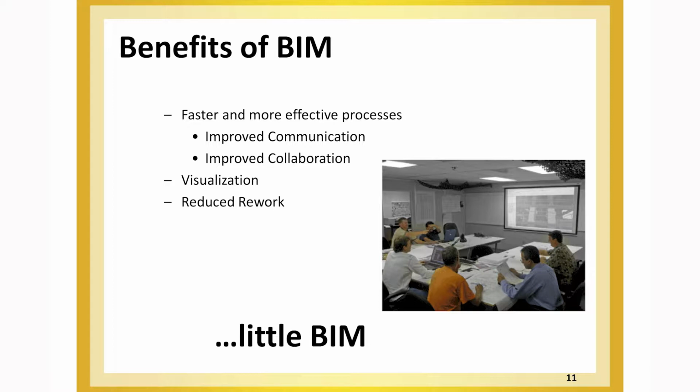Right. But you have your own files with AutoCAD, you don't with Revit, because you're logging on and using somebody else's database. Not necessarily though, no, because once you set up, each company can have their own standard template. So once you've made your template, the only thing you need from the architect is just a reference point. So once they tell you what the reference point is, you can use whatever your template is. It's actually easier than AutoCAD in that aspect because you don't have to worry about layer naming conventions, line weights, pen weights, all of that goes away because now it all becomes defined within your template.